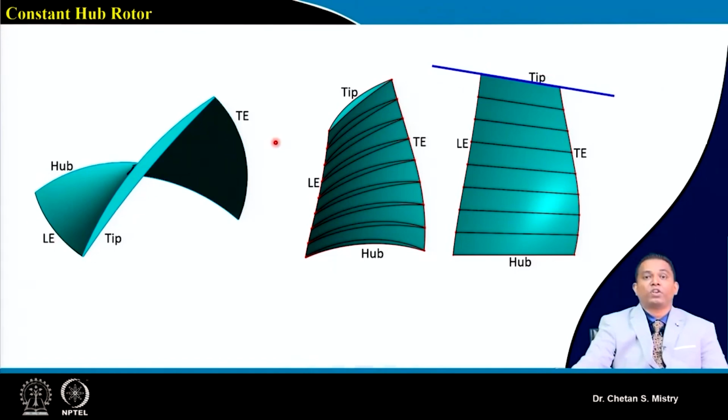Same way, this is my transonic compressor. That's the reason why we have selected a DCA aerofoil. Here, if you look, this represents how my blade angle varies all the way from hub to tip. Okay, there is still scope: you can modify the loading near the hub and reduce this turning angle. Now this represents my constant hub diameter configuration.